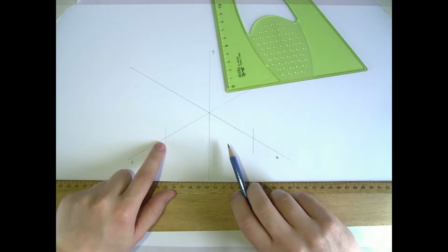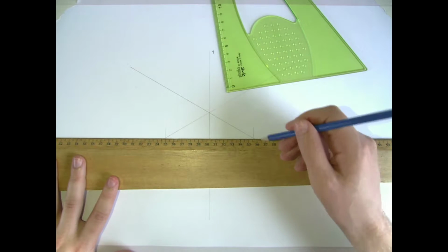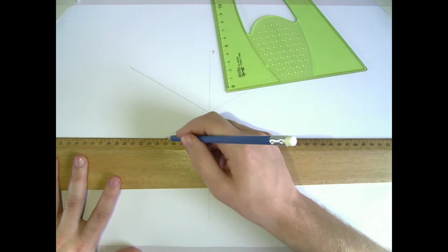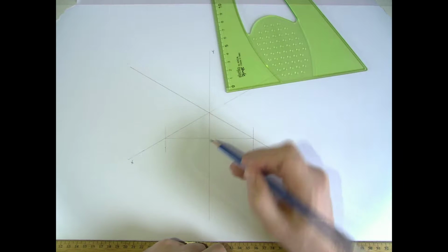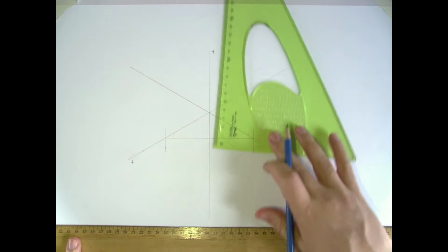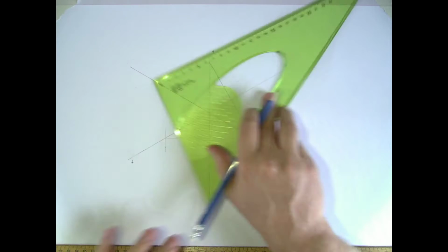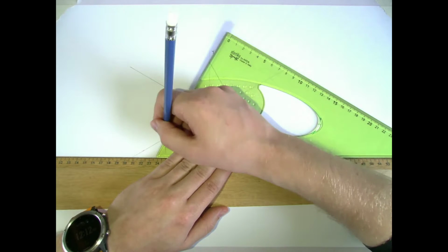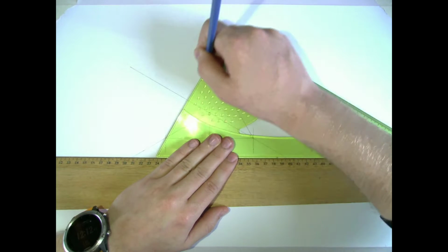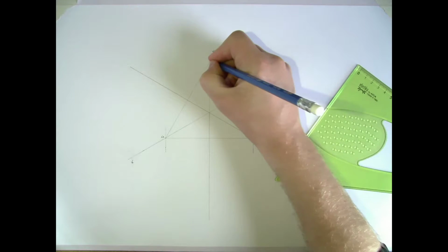Now when you have these two points marked, 53 here and 53 here, it's important to check that they end up being horizontal. They're supposed to be, because they're supposed to be at 90 degrees, or perpendicular, to the Y-axis. If they're not horizontal, I suggest you stop and restart this part of the question, as it will cause difficulties later on if they don't line up. So completing the equilateral triangle, have 60 degrees going this way and 60 degrees coming this way also. These should cross at a single point up here. So we've got A, B, and C.